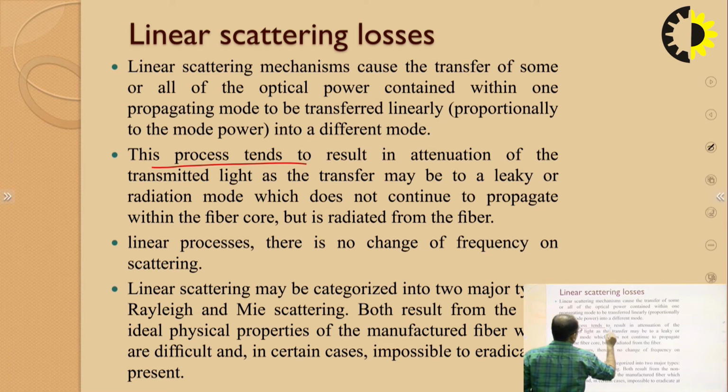So this process tends to result in attenuation of the transmitted signal, as the transferred energy or transferred mode may be a leaky or radiation mode, which does not continue to propagate within the fiber core but is radiated from the fiber.